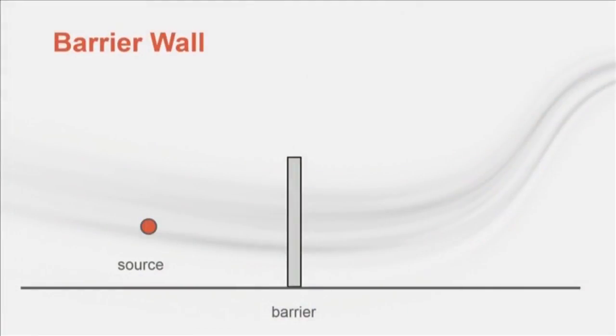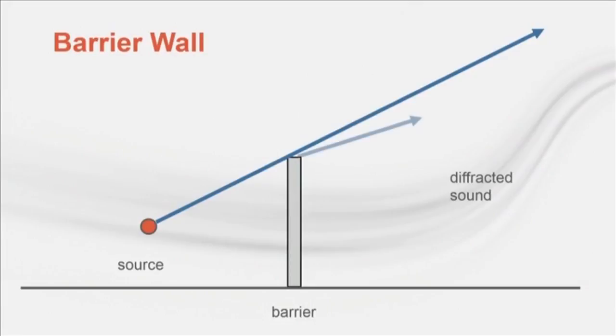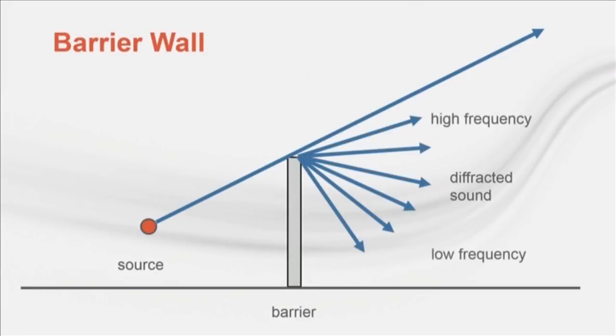There's one more quality of diffracted sound to consider. The amount of diffraction is frequency dependent. High frequency sound doesn't diffract very much, but low frequency sound is able to bend around the top of the barrier. What that means in practice is that the barrier attenuation is not the same for all frequencies. If you look back to the barrier calculation Eric did, you'll see that the attenuation provided by the barrier was 8 dB at 63 Hz and increased to 22 dB in the higher octaves.